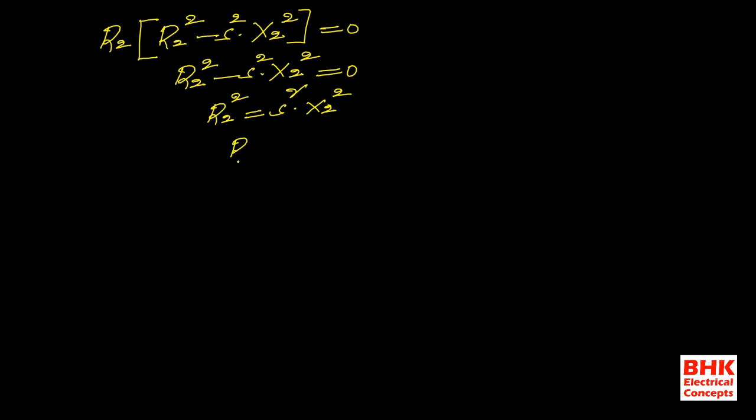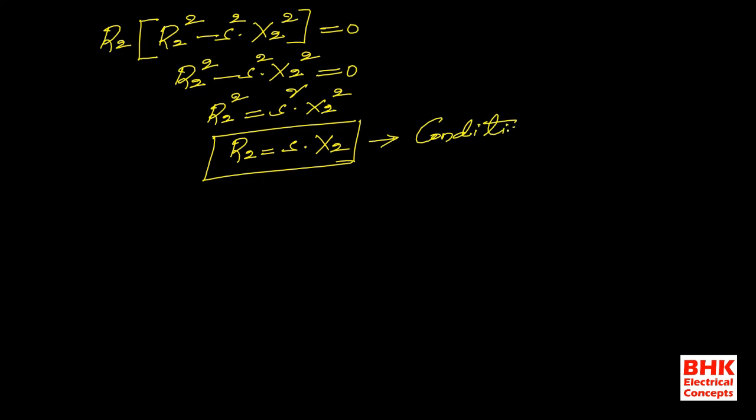From this we can directly write r2 is equal to s times x2. Okay, so this is the condition required to get maximum running torque. Okay, to get maximum running torque.